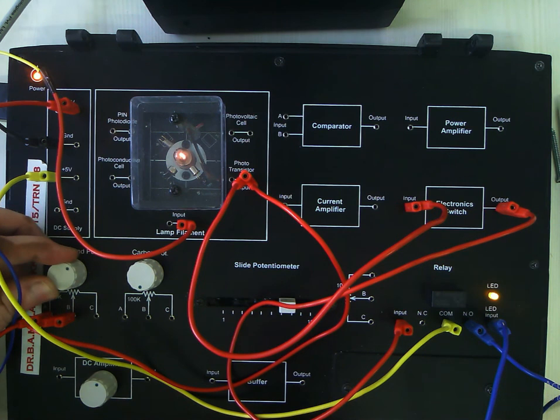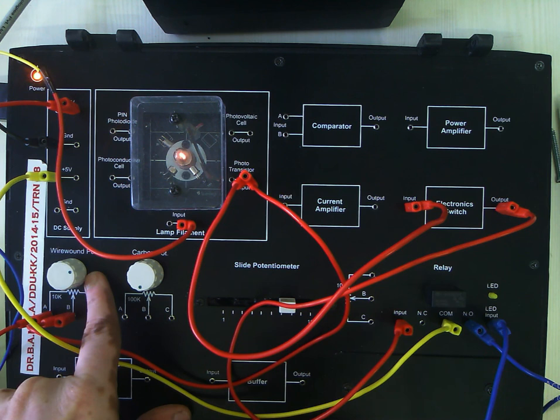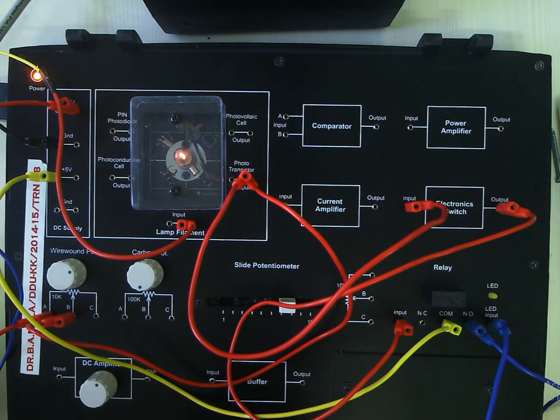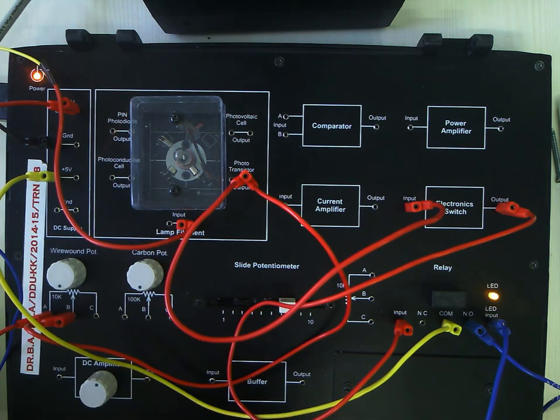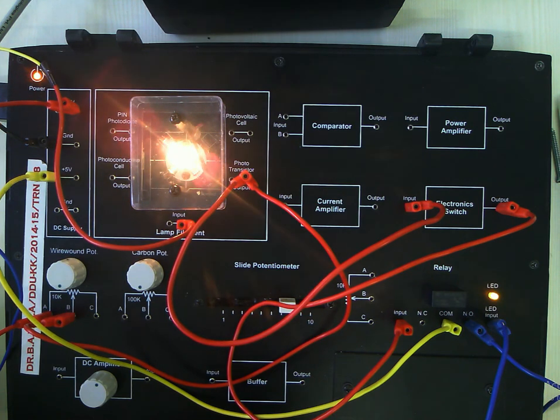You can see. So you can change this value of collector resistance to decide at what intensity of the ambient light this LED will be energized. Now you can see that even if there is very feeble light, the LED will be off. Now I will again get it back. I will make it minimum. Now you will see that you need a very, even at that intensity, the LED is working.